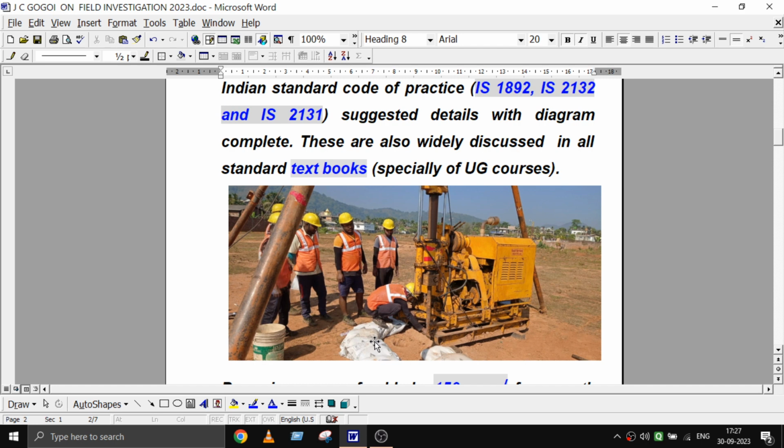is inserted underground with a very high pressure, about 20 kg per cm square, that is 200 ton per meter square, which normally affects the soil of the entire bore area up to a reasonable radius.